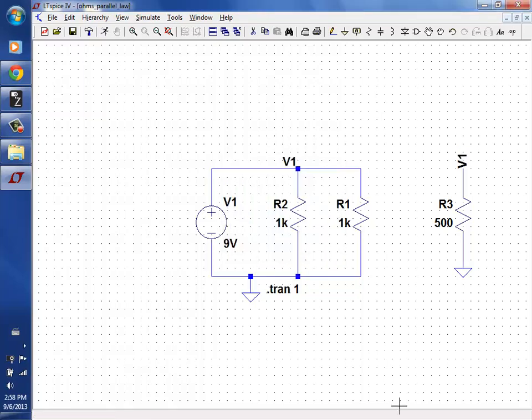Here's how you create frustration. These two nodes are now connected. It's exactly like I connected a wire from here to here. Let's prove it. If I go to the wire and I right click on the wire and I hit highlight net. If you don't understand this, you will get frustrated when you're doing your circuits, especially if you copy one and you copy it to another place and it has the same node names.